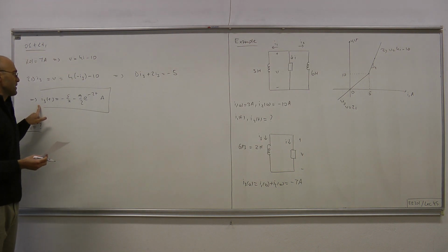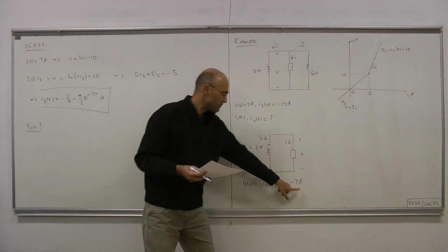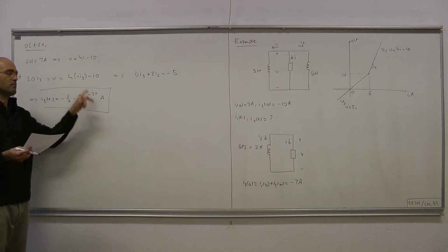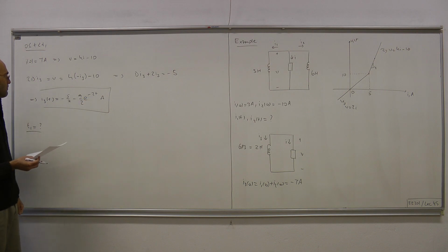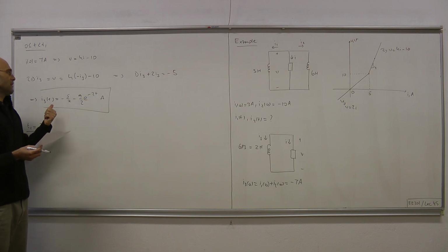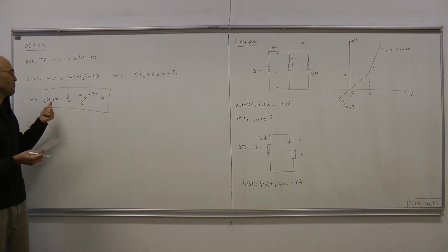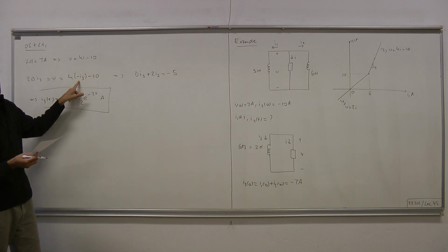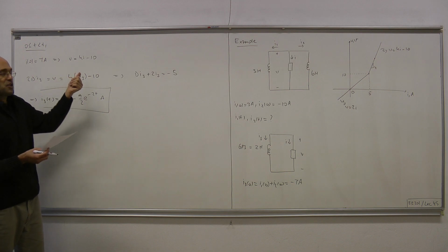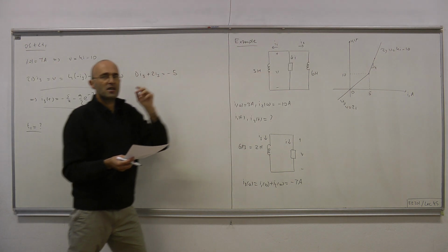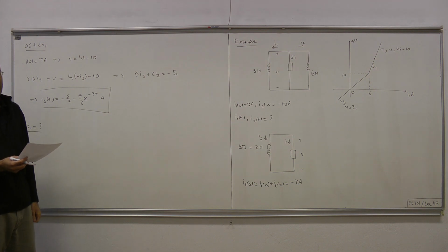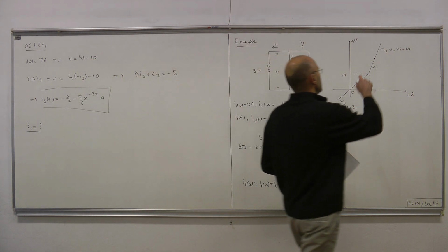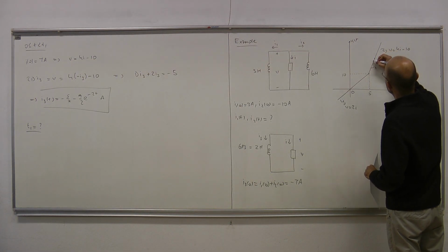So this is I3. It starts at -7 and it's heading toward -2.5, because this exponential term will disappear as time goes on. The natural frequency is negative. I3 is therefore increasing from -7 toward -2.5, and since I is minus I3, the current of the nonlinear resistor starts at 7 and is going toward 2.5. Well, it's intending to go to 2.5. So what happens is we start here and we're moving in this direction.